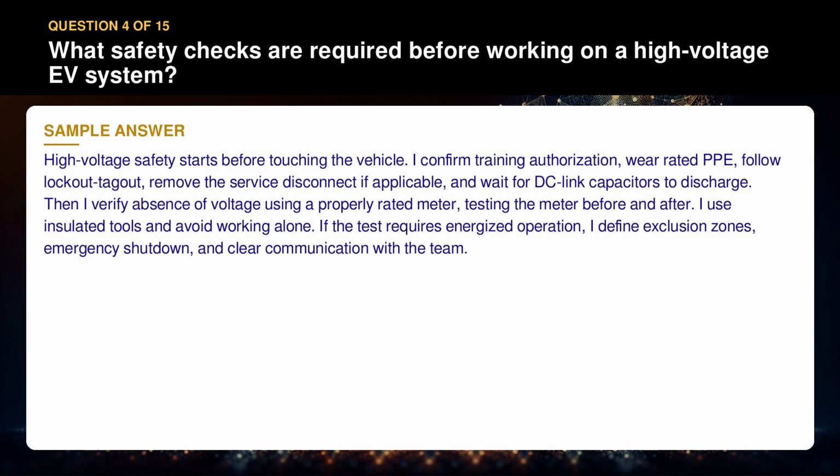capacitors to discharge. Then I verify absence of voltage using a properly rated meter, testing the meter before and after. I use insulated tools and avoid working alone. If the test requires energized operation, I define exclusion zones, emergency shutdown, and clear communication with the team.